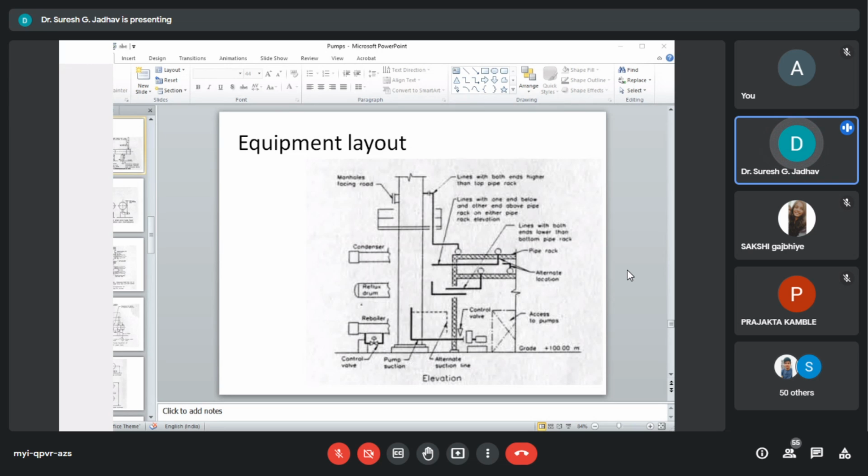This will facilitate maintenance as well as access to instruments and valves. From a layout point of view, it is preferable to have equal platform spacing and orientation of bracket lineup along the entire length of the tower.